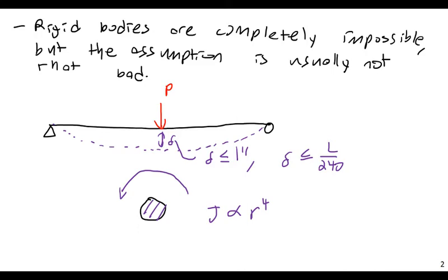It's going to explode because one day it was hot outside or something really stupid like that. So we add tolerances to all of our real world engineering problems, and that takes care of all of these really tiny changes that come as a result of our simplifying assumptions. Actually, in this case, the expansion might help you a bit, because if you expand the radius, your polar moment of inertia increases, and that decreases the amount of stress within the material. So that might actually help you in that case. But anyway.